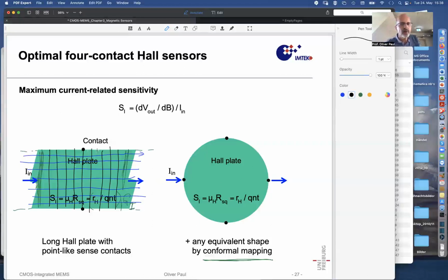and the upper boundary here is now this upper boundary here, and this lower boundary here is this lower boundary, and similarly for the other boundaries. And the extended contacts that we had here, but very distant, become point contacts on this. And the current lines that you now have are circles. So there are circles that all pass through these contacts, and this is the distribution of the current lines, and the current density is equal to the density of those lines that pass through the sample.